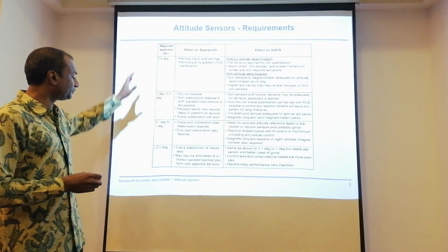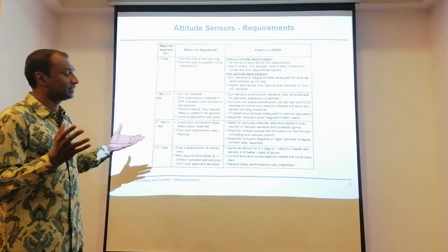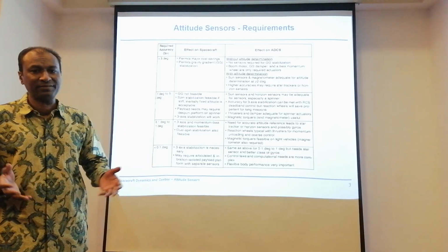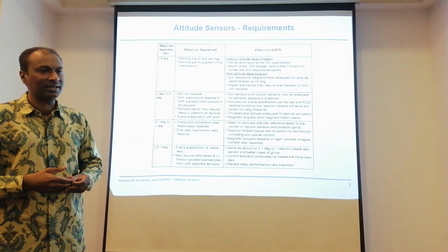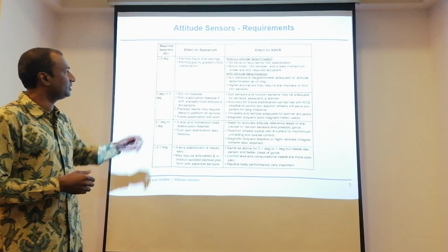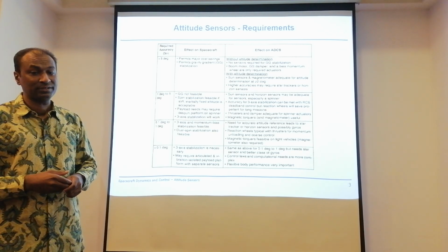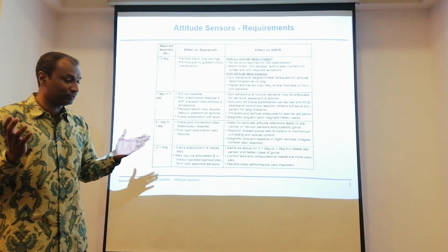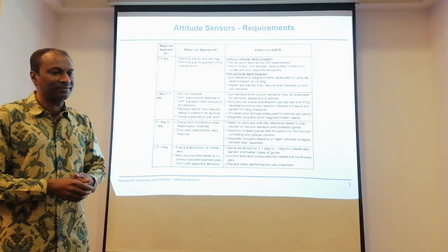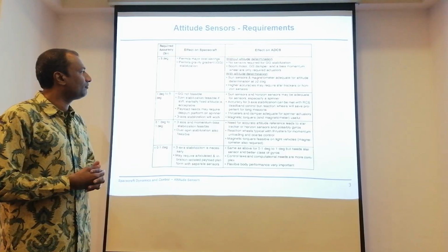When you look at all these options that we have for their effect on the spacecraft, the most primitive way is a gravity gradient stabilized satellite. You cannot expect much attitude accuracy, more than 5 degrees. Technically, it's a passive way of stabilization. The first one means that you don't depend on any sensors. There's even no point of having sensors, because you can't control it. So it's like a free fall, as you can see.